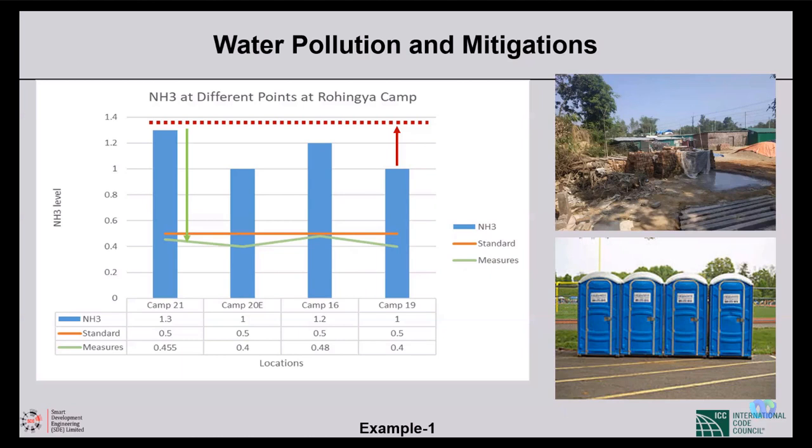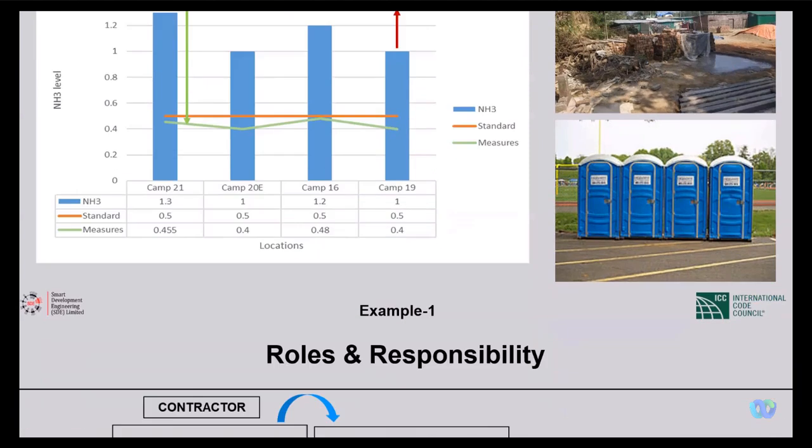That will be higher because additional tubewells will be installed for construction purposes, and also pit latrines will be there for the labor. So we mitigate. We want to say no more like that. You have to use proper latrines, no more portable latrines type of thing, so it does not contaminate, go to the soil, to the groundwater, or to the drinking water. That is important.